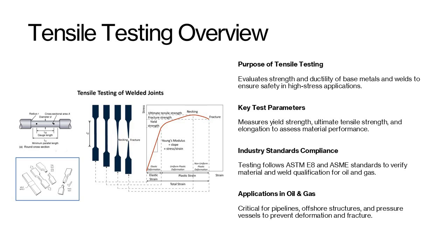project specifications. Tensile testing is essential during procedure qualification records, PQRs, where it confirms that welding procedures produce weld metal and heat-affected zones with acceptable properties. The process also ensures that base metals delivered to site comply with mill certificates and fabrication requirements.